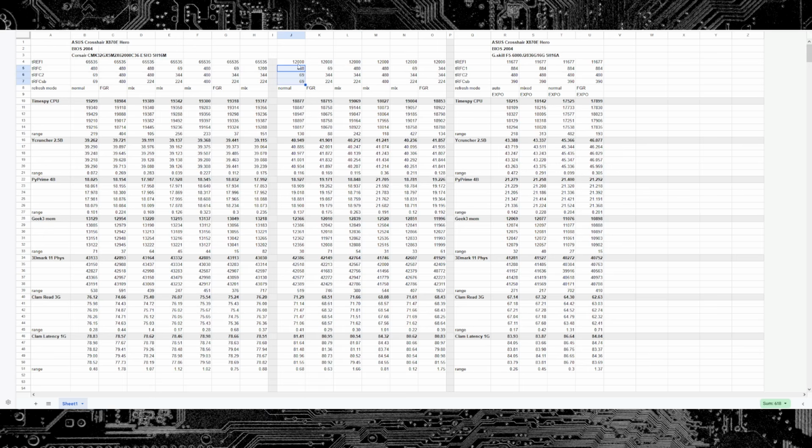Compared to normal mode with, you know, 12,000 refresh interval. So you can just imagine what FGR would be like. It would just be a complete disaster because you're dividing the refresh interval by 2 and the TRFCs are terrible. But anyway, badly tuned mixed mode is not great. Properly tuned mixed mode is probably the fastest thing you can run right now. Again, it depends kind of on what memory chip you're running.